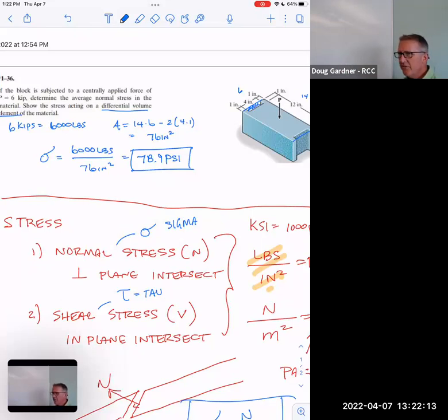Does that make sense? Aren't there materials that would not be able to handle it? And notice that's per square inch. Don't forget to stop and think about that. That's 78 pounds, roughly 80 pounds on every tiny 1 by 1 inch. So it's spreading out that 6,000 pounds. And as I said before, if you were going to puncture that, you might have to put a steel plate on the top of it to make sure the load gets distributed everywhere. Because if you put a post in the middle of that, probably those little tiny protrusions aren't going to be helping.